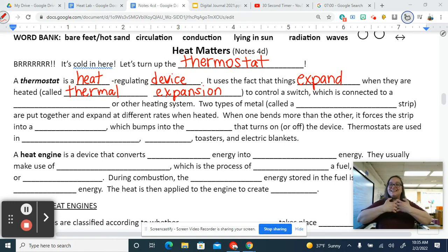So they put in those metal teeth, it's just a metal grate with these teeth, and they slide together when it's hot and they pull apart when it's cold, but not enough for the bridge to fall apart, just a little bit. When they build railroad tracks, they don't put the two rails right next to each other because when it got hot and expanded, they'd buckle. There's a little bit of gap, and that gap allows for that thermal expansion. And the gap isn't big enough for those big old train wheels to mind it. So thermal expansion is the fact that when things get hotter, they get bigger.